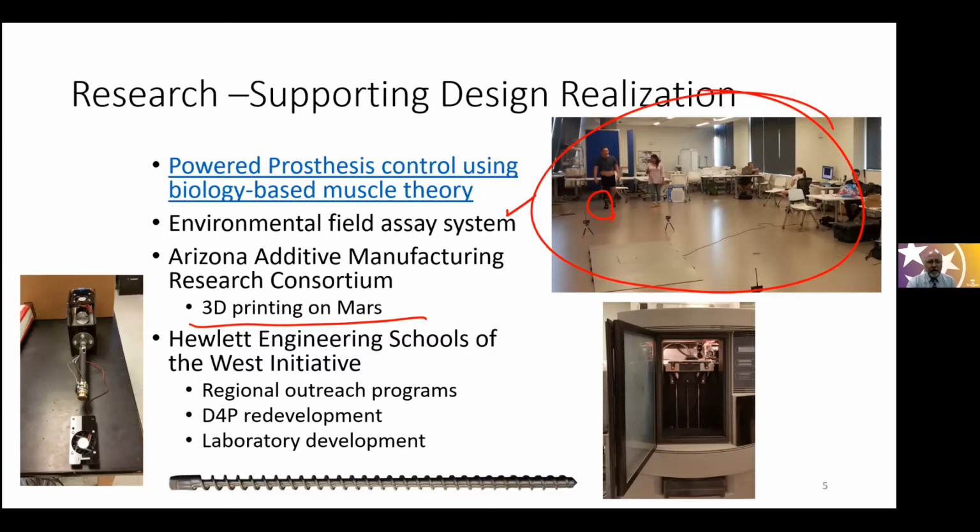Basically we used hobby extruders for 3D printers, and then we pour sand into it at certain measured amounts to get highly filled materials. And the nice thing about that is that with the hobbyist level, they weren't that expensive. You could tear up the screws and the barrels and just remake them very quickly, and it wouldn't cost much. One of my design initiatives was to redesign the way screws were designed for the extruders to take care of this highly filled material, because it would rip the flutes right off.